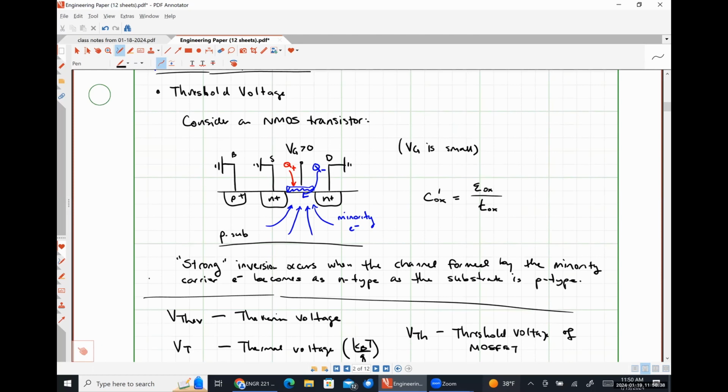When we were talking about this particular picture right here, where our source and drain are both shorted to ground, even if our gate voltage is high enough such that we've met or gone beyond our threshold voltage, we shouldn't see any current flowing in the device, right? So even though it's on, it's still just really acting like a capacitor. And the reason for that is because our current flows from the source to the drain or from the drain to the source, depending on if we're dealing with positive charge carriers or negative charge carriers. And if there's not a potential difference between the source and the drain, we shouldn't see current getting pushed in one direction or the other, right?